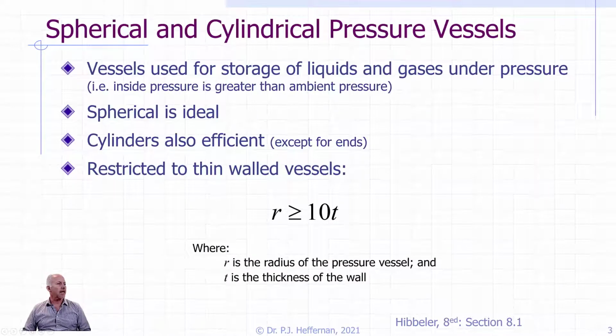So what exactly are they? They're vessels used for storage, typically of liquids or gases that are stored under pressure. And the inside pressure is greater than the ambient pressure, so they're pushing outwards, which pushes the pressure vessel into tension to contain that increased pressure inside.